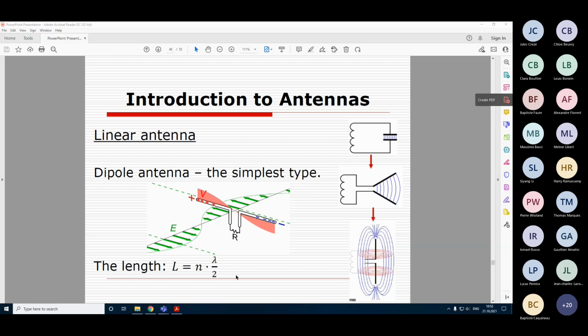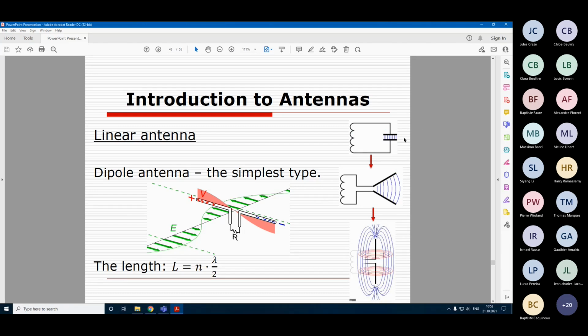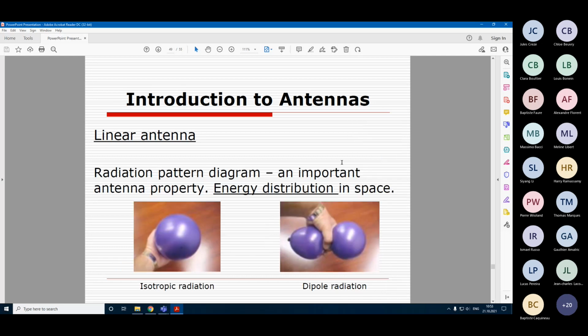This is also related to the fact that the Earth is not flat and the horizon can prevent receiving the signal. So that's serving two purposes. We increase the height for greater coverage, and we use a longer antenna to be more energy efficient, to increase the power of the transmitted signal.